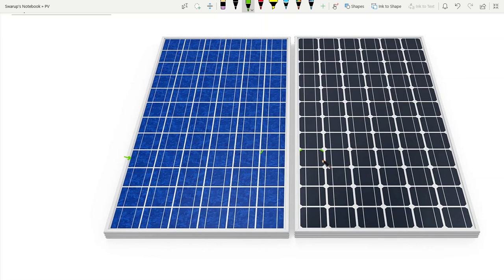But in a single crystal, there is a particular growth orientation, because single crystals are grown by Czochralski, right? So you get this kind of big ingot, you remember? And then from the ingot, we slice them off. Roughly, I'm just drawing it. While slicing, we mark which direction it has grown and which direction we are going to cut.